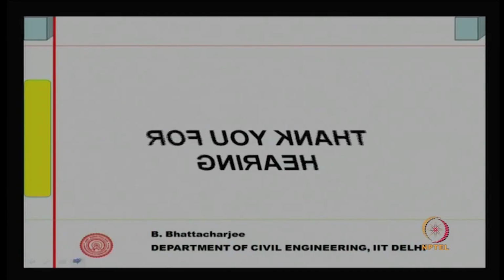So, we can summarize the whole thing now. This is the last lecture of this module. We have looked first into the chemical admixtures and then into the mineral admixtures, and for the mineral admixtures we first looked into their characterization, then into their effect on fresh concrete, then on hardened concrete, creep, shrinkage, strength, and then the durability. As far as durability is concerned, they perform better, except for carbonation, where carbonation depth tends to increase with addition of mineral admixtures. So, I think with this we can conclude this module, and thank you very much for hearing.